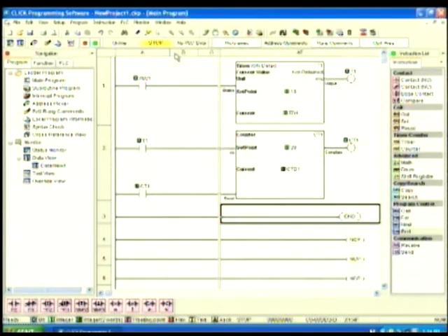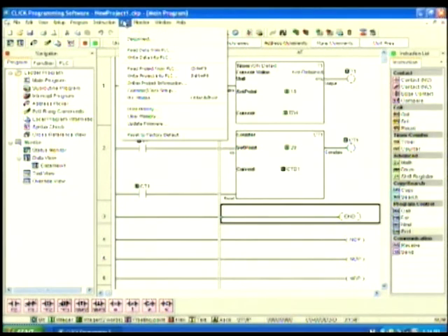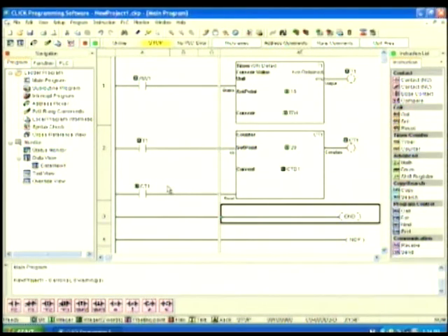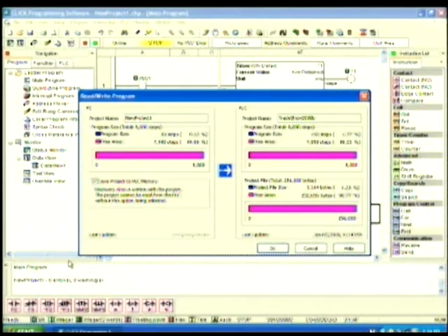So now we're at the point we need to drop our project into the PLC, right? Right. So we go back to the PLC menu, and we go down here where it says Write Project into PLC. Click that. It's going to start compiling. You see a little compile window coming up down here at the bottom of the screen where it's going to tell you if you have any errors, what the errors are, what line numbers they're on, and what's actually wrong with it. So you take and do that.